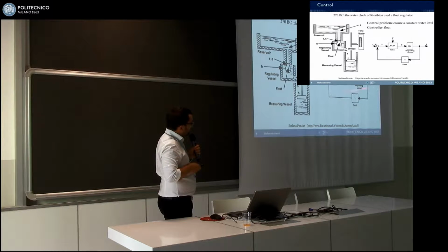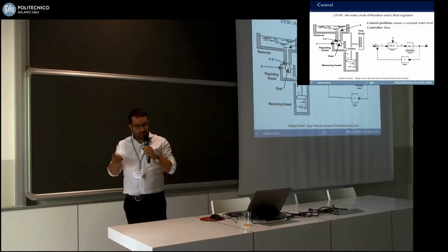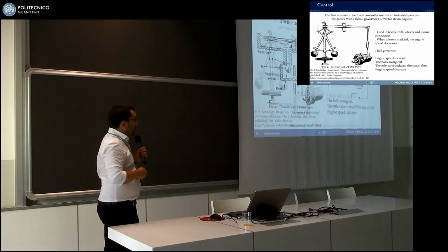So this is the feedback mechanism: the float tries to regulate the error, so the actual value and the desired value, and the valve, which is the controller, tries to give the correct input to the regulating vessel. So it's not a new concept, the feedback system.